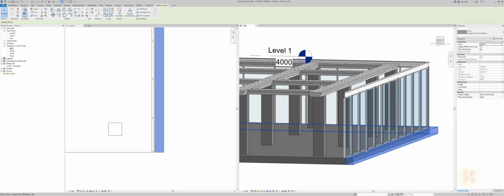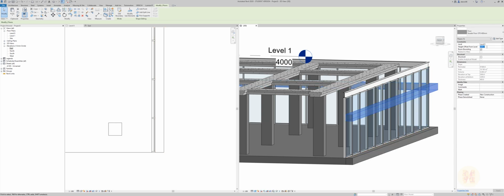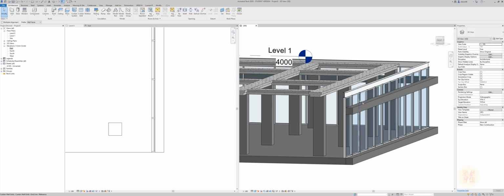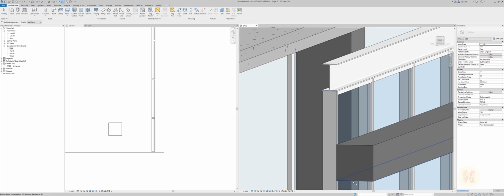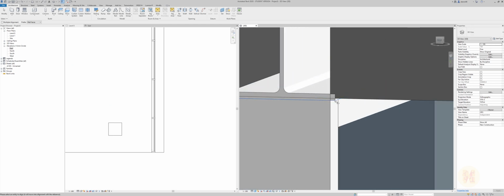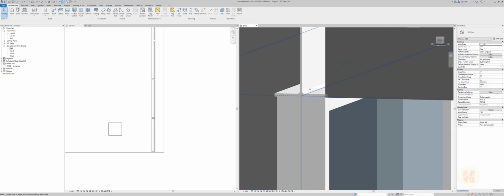So you can add more detail if you want, but this is what I want. And let's copy it. I want to copy it, and I will put it also under this line. Let's copy it to the same place. Okay, and I will just change the height, 2600 millimeters. Let's check it out. No, it's not enough. Let's do 3000 millimeters. Okay, I will use a line, it's much faster. Let's use this side and that side. Okay, pretty close. We're done with that.